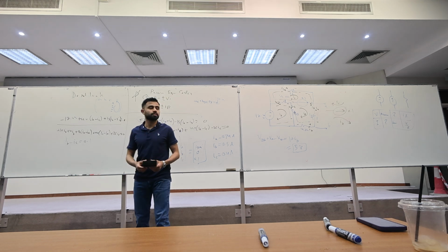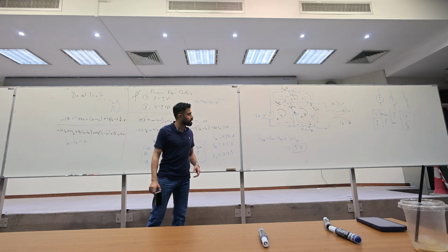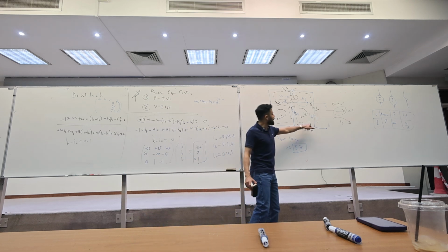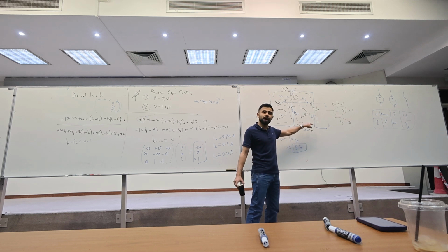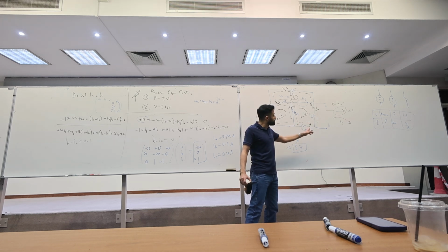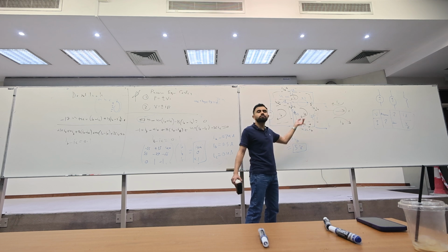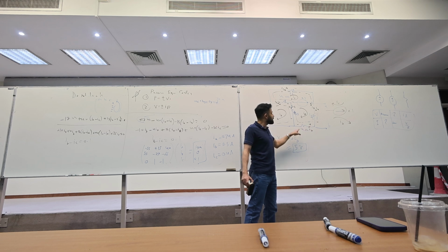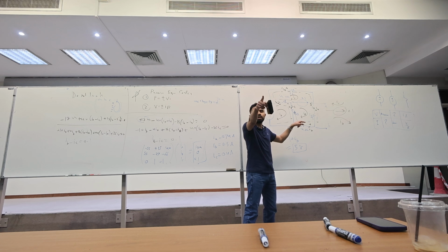Why do we reverse the sign for resistance? It's not that we reverse it. If you put it minus and plus, it will be a voltage rise. But because IB enters from the negative, you have to fix it with a negative sign. So ultimately, it will be minus 4 times IB. If you put minus and plus, passive sign convention will get you. If you use plus minus, no passive sign convention, but it's a voltage drop.